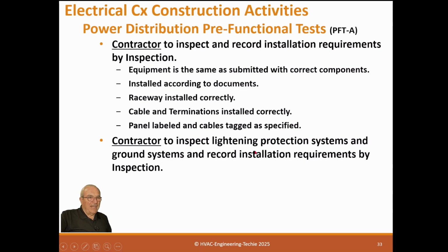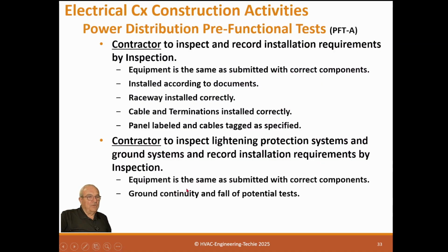Contractor to inspect lightning protection systems and ground systems and record installation requirements by inspection. Equipment is the same as submitted. Ground continuity and fall of potential tests. Now, this ground test is really important. This is how they test ground rods.